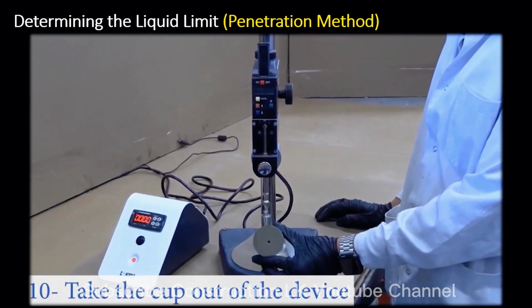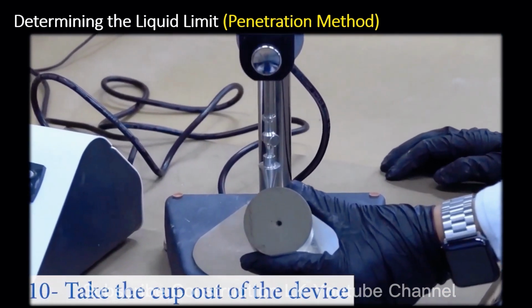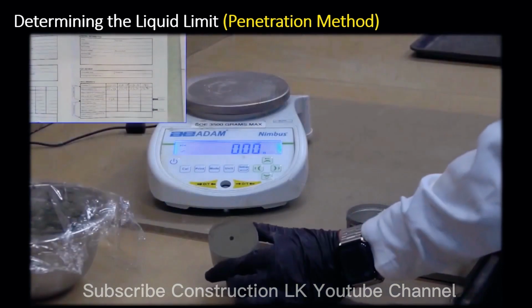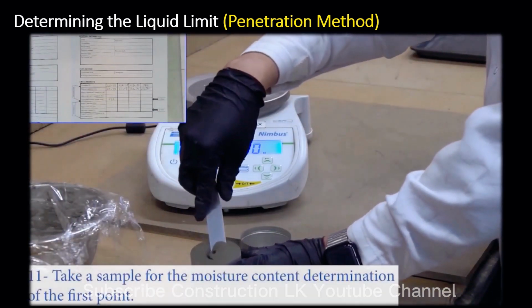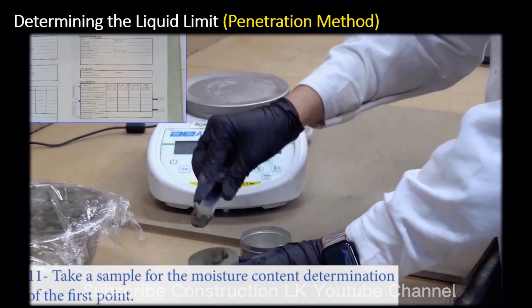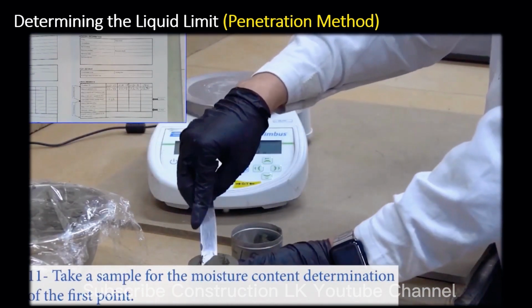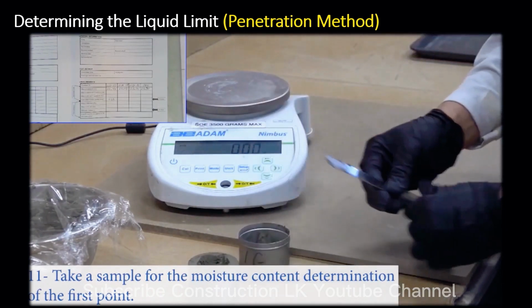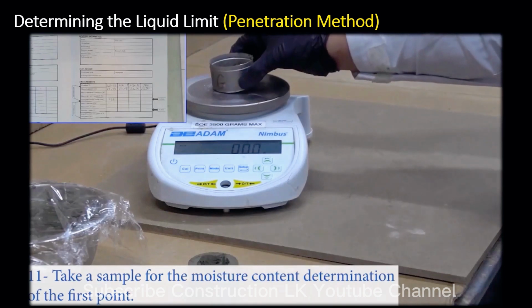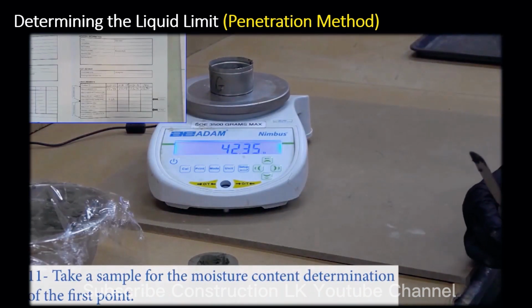A little more of the soil paste is added to the cup and the test is repeated until a consistent value of penetration has been obtained. Then a sample is taken for the determination of the moisture content. The entire test procedure is repeated at least 4 times using the same soil sample but increasing the moisture content. The penetration values should cover the range of approximately 15 mm to 25 mm.